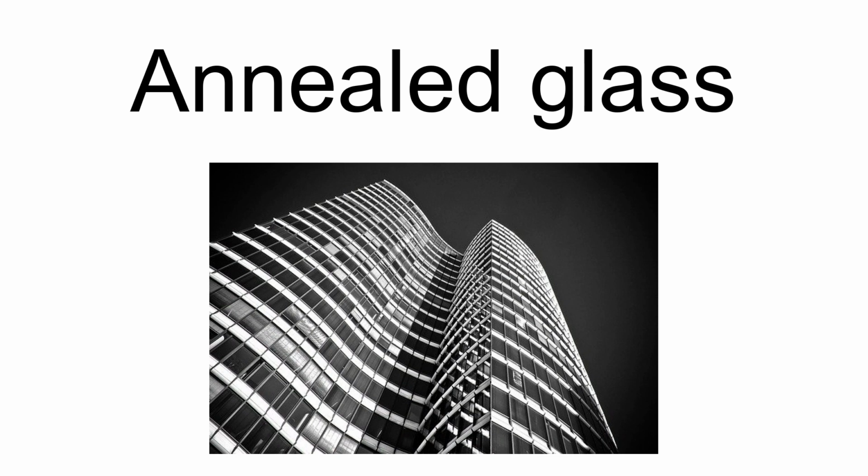Annealed glass breaks into large, jagged shards that can cause serious injury and is considered a hazard in architectural applications. Building codes in many parts of the world restrict the use of annealed glass in areas where there is a high risk of breakage and injury, for example in bathrooms, door panels, fire exits, and at low heights in schools or domestic houses. Safety glass, such as laminated or tempered, must be used in these settings to reduce risk of injury.